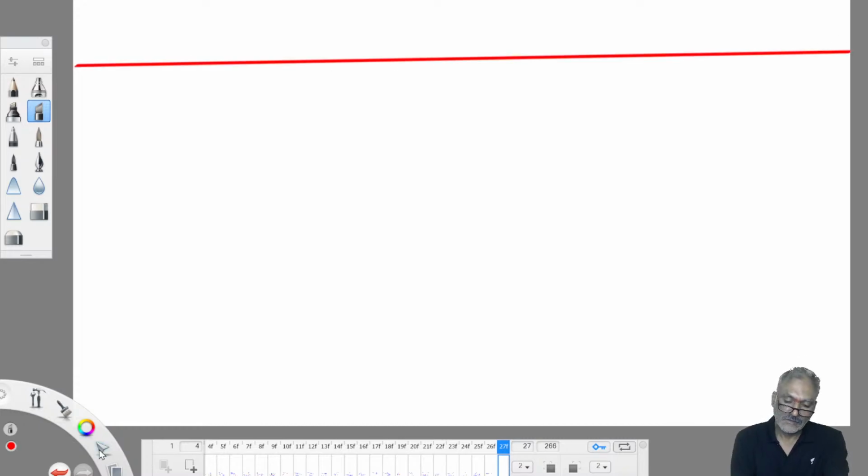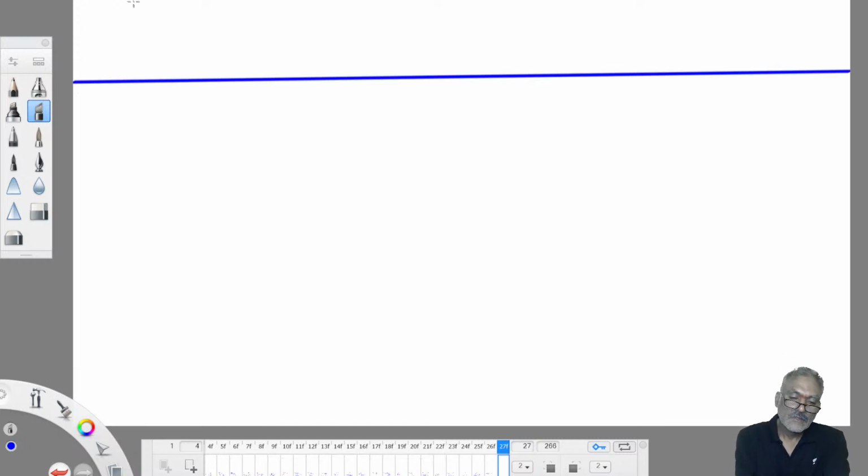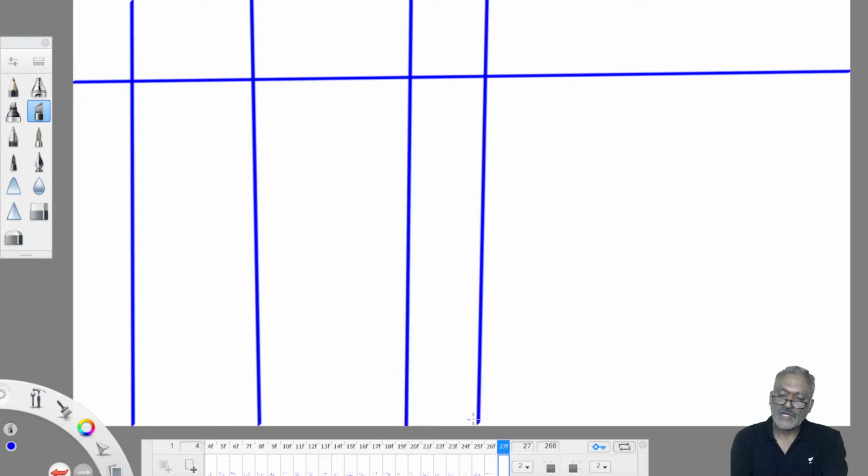So one unit hydrograph is given. From the unit hydrograph we can work out the direct runoff hydrograph. To this, if you add base flow, you will get a flood hydrograph or storm hydrograph.